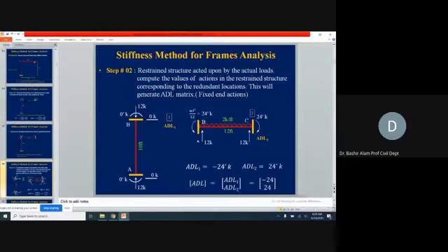So when it can slide in the vertical direction, it means this 12 kip, when it starts sliding in the vertical direction, is going to be transferred to this BA member. And this joint must be in equilibrium. So this 12 kip can transfer to this B joint here. It's the same joint B. Because of that sliding, because that is still permissible here, we have stopped only D1, which was rotation. So this 12 kip is in the upward direction. Here it is going to be in the downward direction. This joint is in equilibrium.